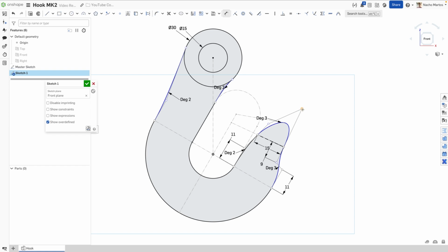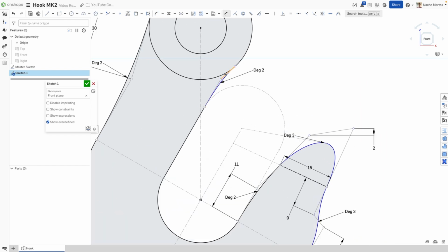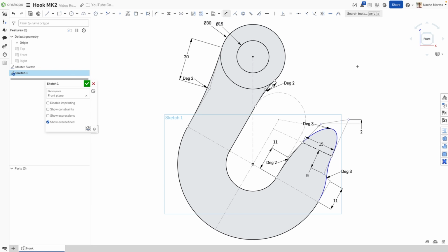Now that's relatively dimensioned. Let's also make the hook a little bit more controlled. We're going to make that 2 centimeters. Now that's really the geometry we're getting after. I'm just going to clean this drawing up for readability. This is 2 centimeters. Now let's just do a little bit more constraining to close out the sketch as much as we can, and just facilitate this process. And we will dimension this line 6. All right, so that makes our sketch mostly dimensioned.